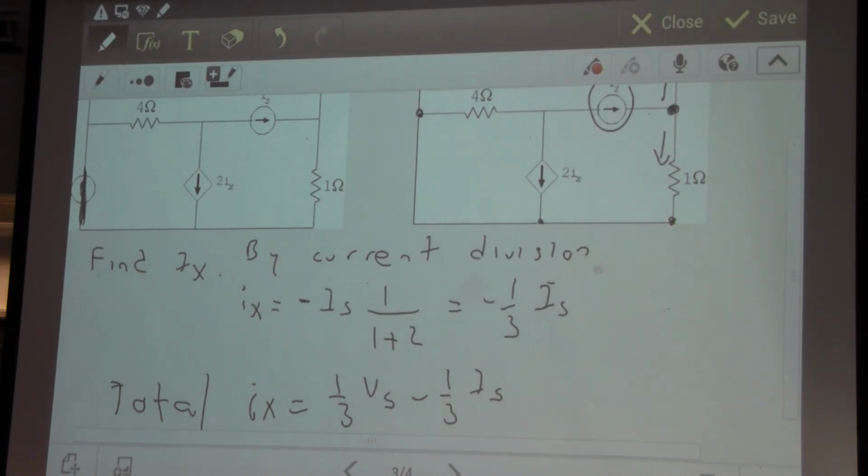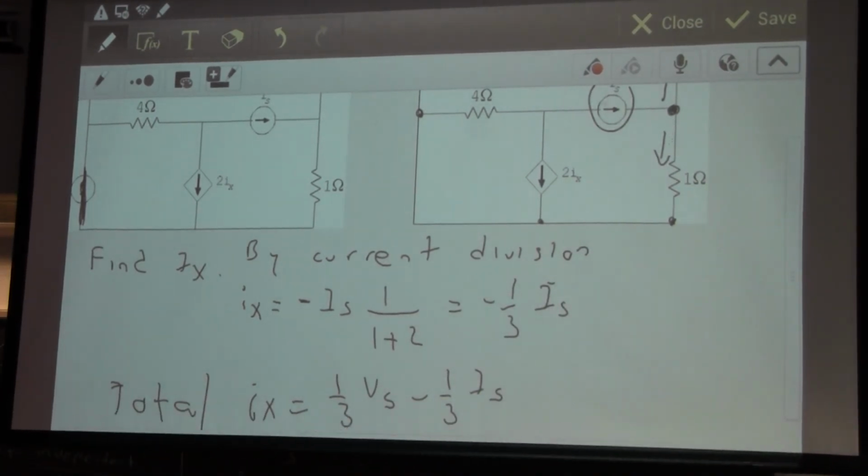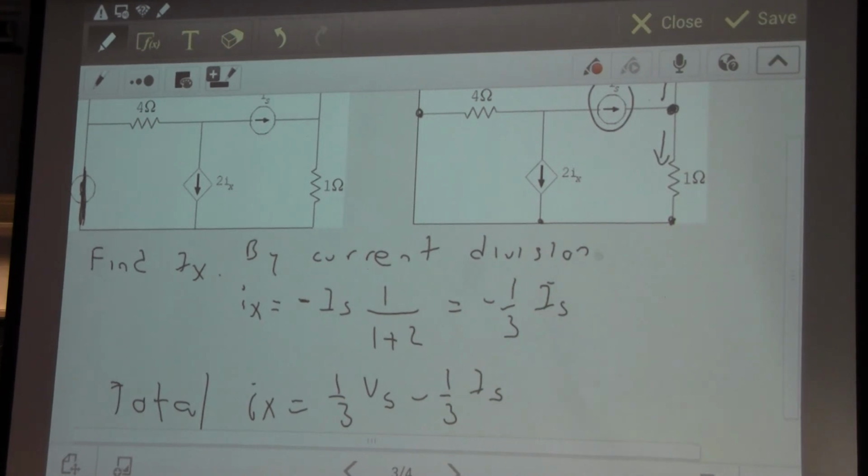And then if you look at your notes, and it's actually behind the screen, so I'm going to pull the screen up just when you guys finish writing. But look at what you had written down for I2 when we solved this circuit using the node voltage. You can also get that by writing the KVL for the super loop, right? Right, you can do a KVL. So there's not a single way of doing it, but you can do it multiple ways.